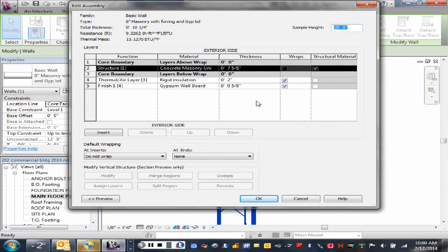Thinking of masonry buildings in general, and as you look around campus even or around the community, how do you make a masonry exterior look unique? You can stagger bricks in and out, or blocks in and out, right? So you can have some steps in it. Oftentimes they might thicken the base a little bit to give it a heavier base look with one color or one texture of block, and then change it as it goes up. The other thing you could do is when it gets up to that reveal area at the top, you could stick those blocks out a little bit to create another layering on the outside.